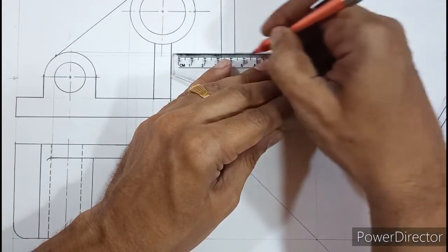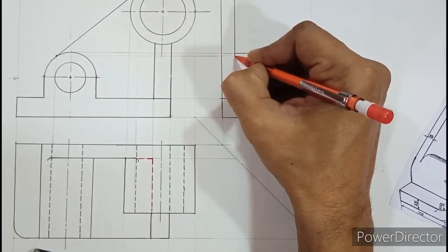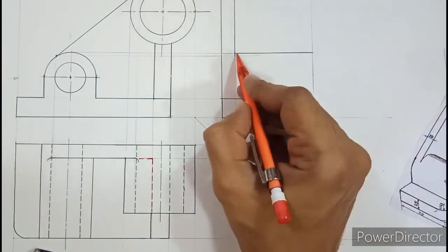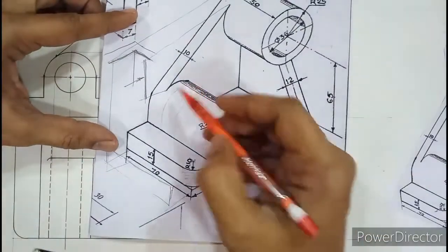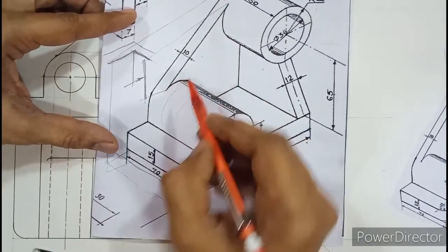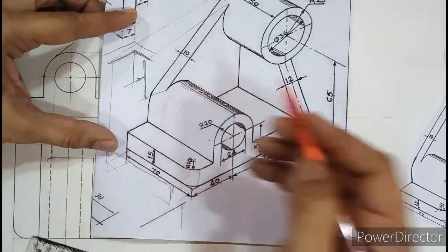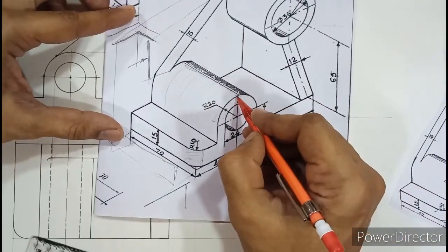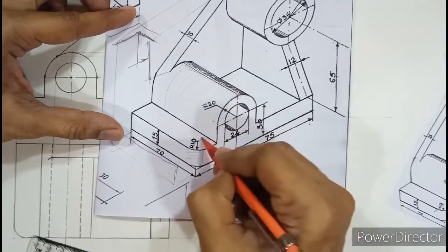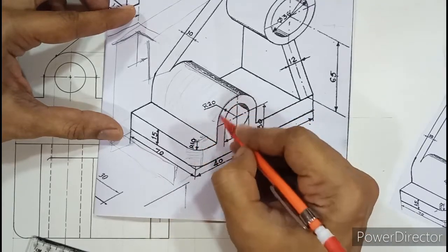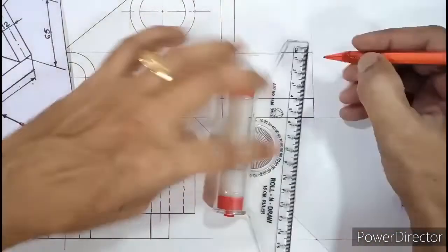So this horizontal line is the boundary, and the rib straight edge is interfering beyond the boundary. Okay, so in the side view, this merging point is beyond the boundary. So boundary is still here and the merging point is a little down. Now apart from that, it is very clear that this circular edge and straight edge in the side view, together are seen as a continuous line. So here we need to close this.